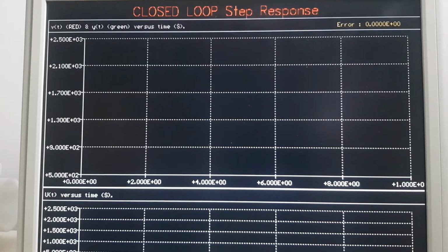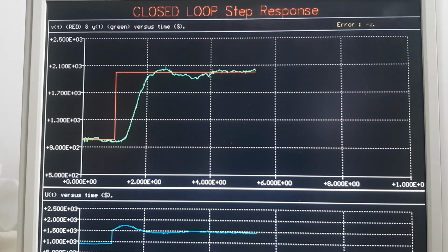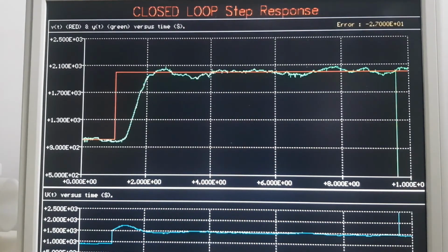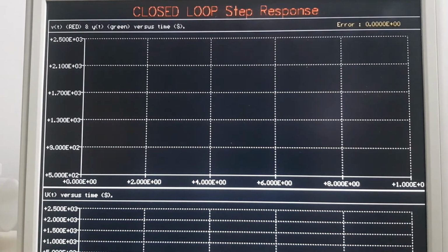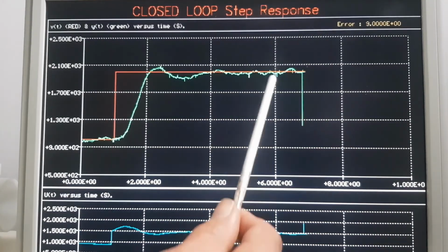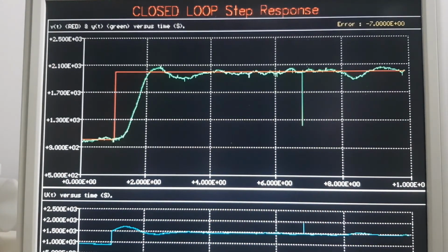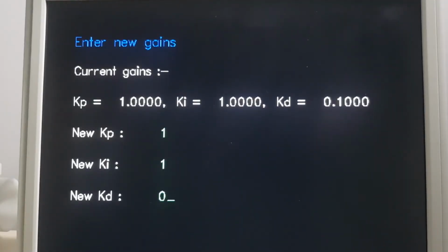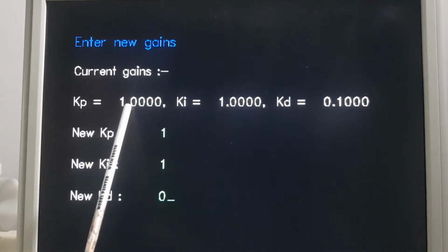So now adjusting them to be slightly different, we get something that looks quite interesting. It's gone up here quite fast, very little overshoot, very little undershoot, and it's going on there. And we consider that to be a well-tuned PI control system. So let's have a look at that working again. So this is a well-tuned PI control system now. It's showing very little overshoot, very little undershoot, and good set point tracking along there as we're going along. So that's our PI control system, but there's a bit more fiddling to get it there. So now we're going to look at PID control. That's choosing all 3 parameters.